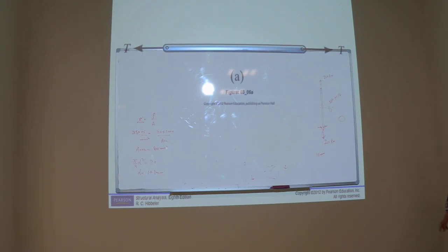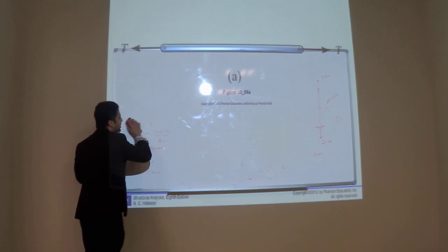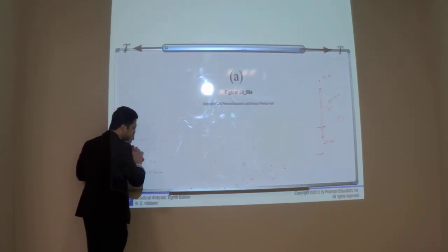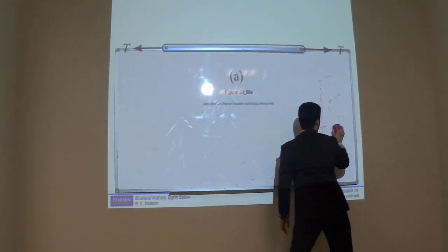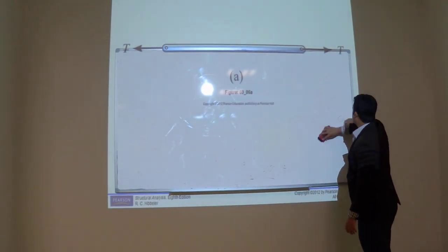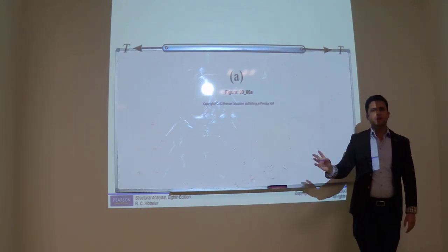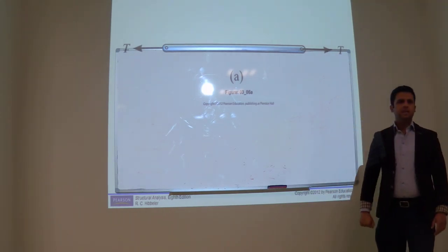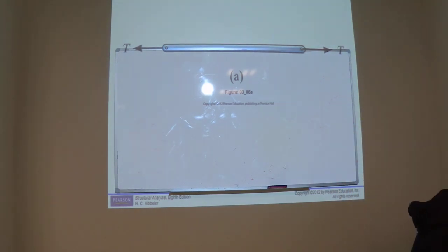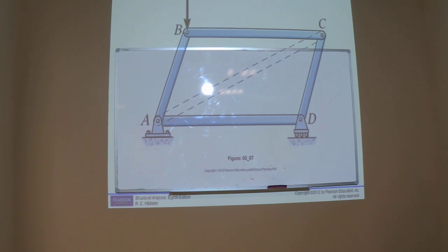That is how we design. Design is very simple for tension, but for flexure it depends on what you want to design for. If you want to design for compression, the procedure is a little bit lengthier because there is one more thing, which is known as slenderness. So we design these members for compression and tension.